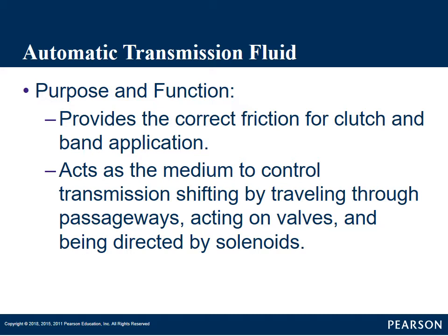Some more purposes and functions of transmission fluid is the friction attributes of transmission fluid, and we'll talk about this. You can put the wrong transmission fluid in, and it doesn't have the correct friction, what we call modifiers, which will cause improper clutch and band engagement, cause shifting problems, and could ultimately cause transmission malfunction.